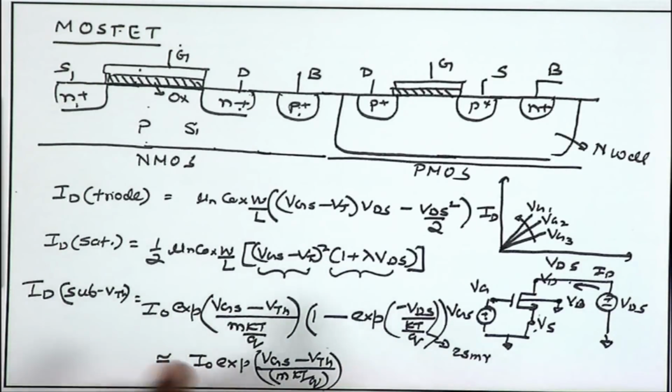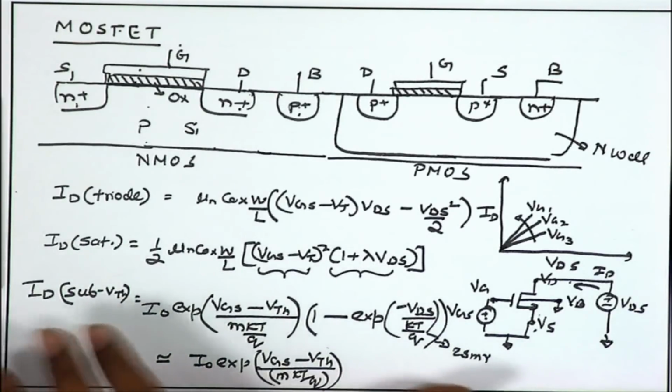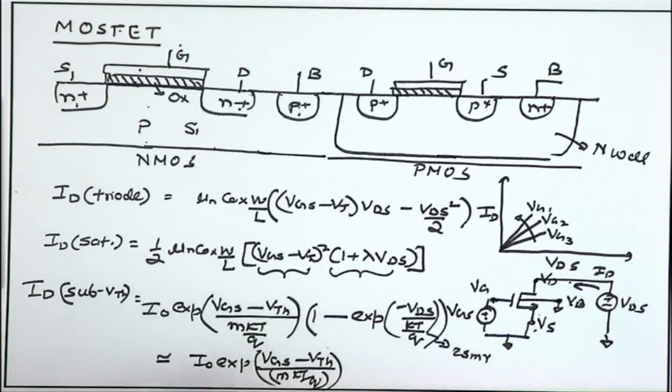Once again, in order to find the output impedance, we may need to take care of the second term. So, that is going to come into the picture at some point. Towards the end, when we are talking about low power front end amplifier design, we may revisit this concept of subthreshold operation and define our parameters in parallel in terms of subthreshold operation, so that in case some of you in future are working on very low power circuits, subthreshold circuits, or teaching these similar topics, you can explain this operation mode as well.